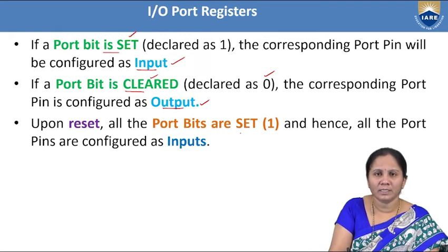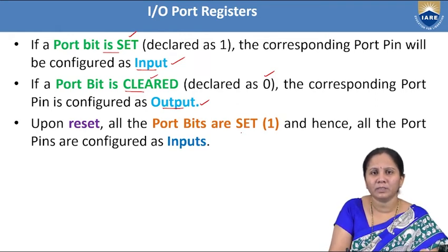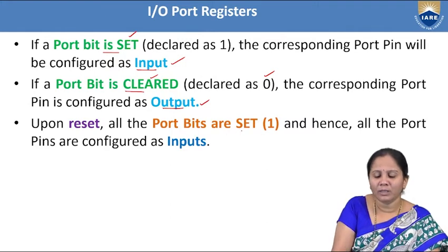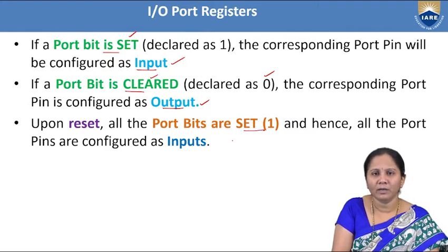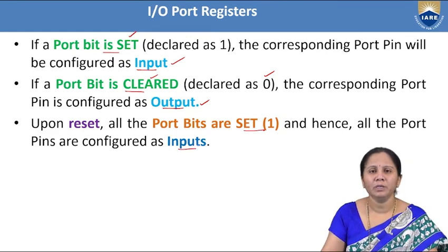Upon reset, that means when the port register is reset, all the port bits are set to 1 and all the port pins are configured as input ports.